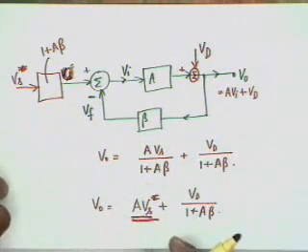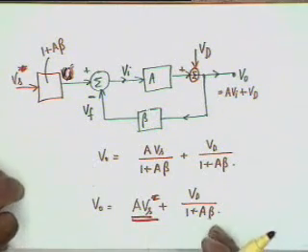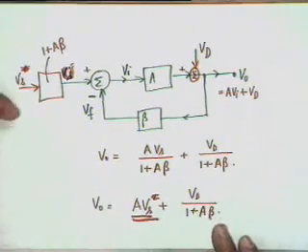Alright. So we convince ourselves by qualitative analysis. In qualitative analysis we look at the kink, and the kink is straightened out. Okay, so nonlinear distortion is reduced. Quantitatively we see that the distortion can be reduced by the factor 1 plus A beta by negative feedback.